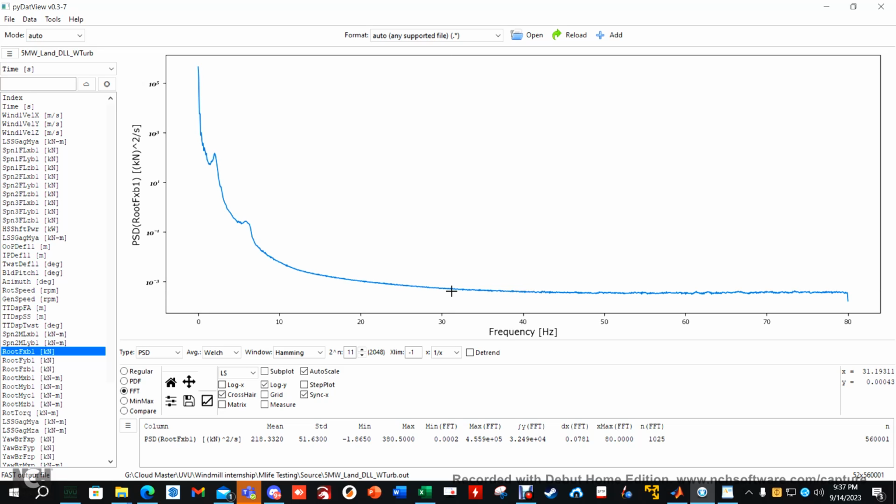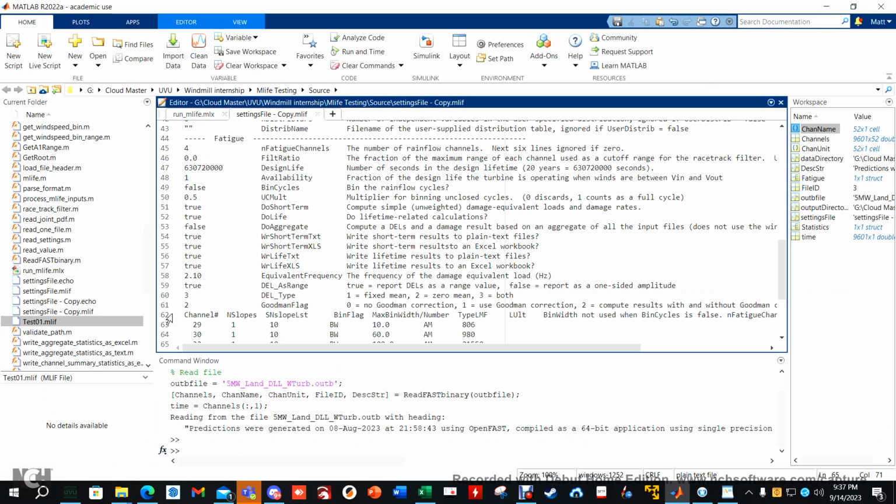That's because I was finding the frequency of the data, not how frequently it was taking the data. So hit FFT, and then you go to the first harmonic. Right here you'll notice here's X and Y, and it's roughly 2.10967. So 2.10. And that is the equivalent frequency that I'm using right here. Default is 1.